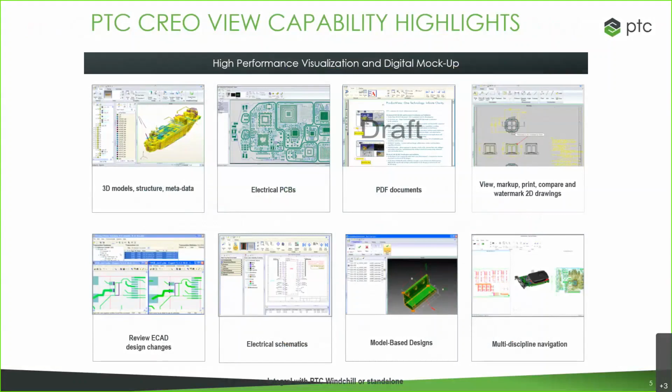You can also use Creo View to make markups. You can put notes on there, take measurements, and show if there is a problem, or if you wanted to make a change request, you can make those notes in the Creo View file and use that as your reference, rather than trying to describe on the drawing, in section H4, there's a fillet that is in the top left corner, please make this adjustment. Instead, you could just put a note that's directly connected to that exact spot, say, this should be this, and show what the current is. So it makes it very clear to do those markups.